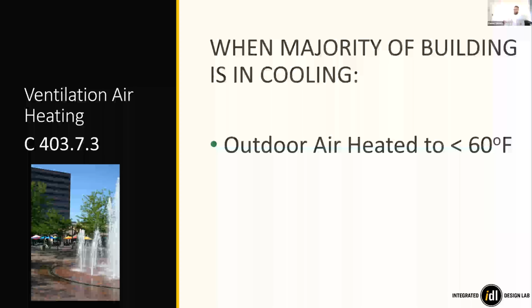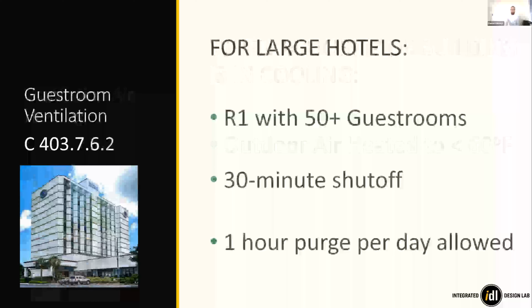But if your building's in cooling mode, then we don't need to basically preheat our air only to cool it down later. That's what they're trying to prevent. They're trying to prevent your building from doing double the work during the summertime, which might happen if you're trying to drop some humidity out of the air.